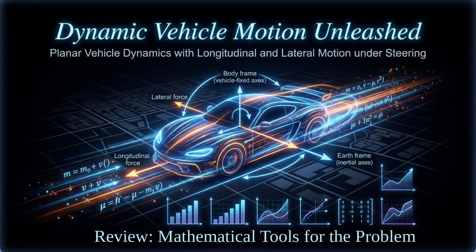Our analysis follows 4 clear steps. First, compute all forces acting on the vehicle, including driving, resistance, and tire forces. Second, use these forces to find accelerations in the vehicle body frame along the forward and sideways directions. Third, transform these accelerations from the vehicle frame to the earth frame, accounting for vehicle orientation. Finally, integrate acceleration over time to obtain velocity, and then integrate velocity to find the vehicle position and path. This structured approach allows us to fully predict how the vehicle moves during a steered maneuver under real-world forces.